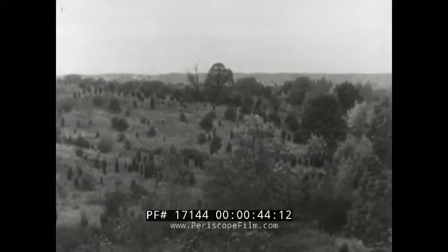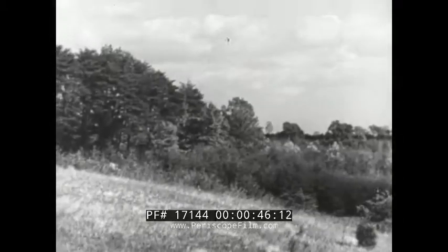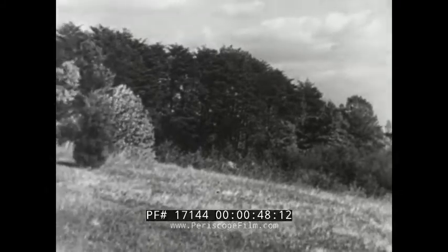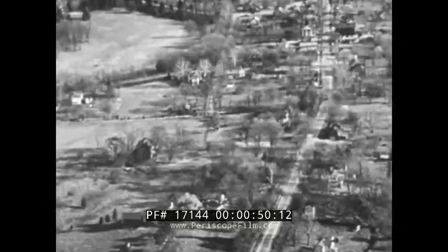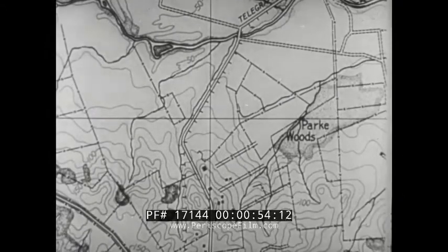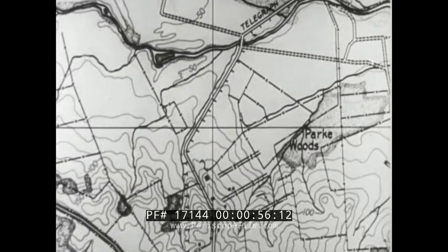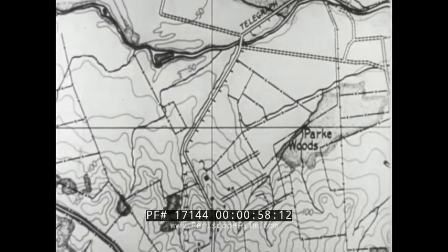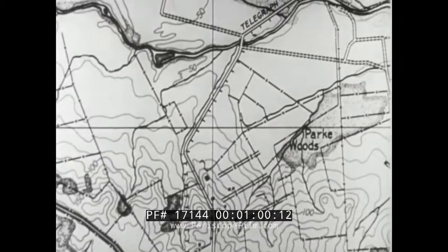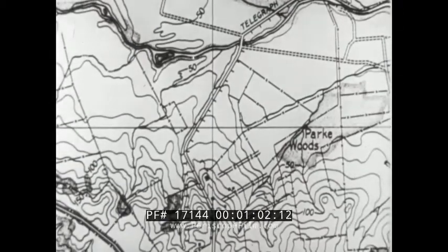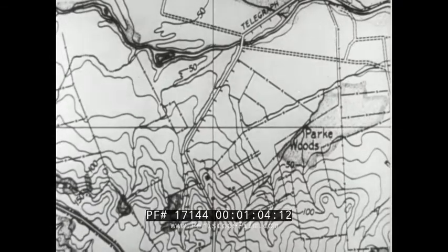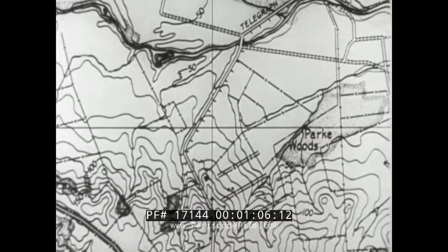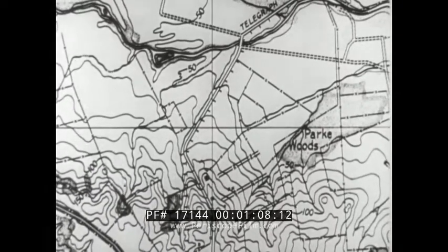A comprehension of natural ground forms such as hills, ridges, slopes, and valleys, including the ability to recognize them on a map, is essential to every military leader. A modern and complete topographical map portrays all these forms, usually by means of conventional signs known as contours. A contour is a line on a map representing an imaginary line on the terrain. It connects points of equal elevation.